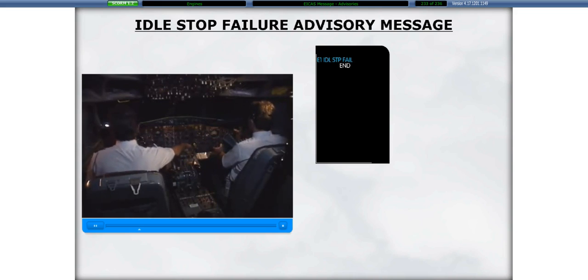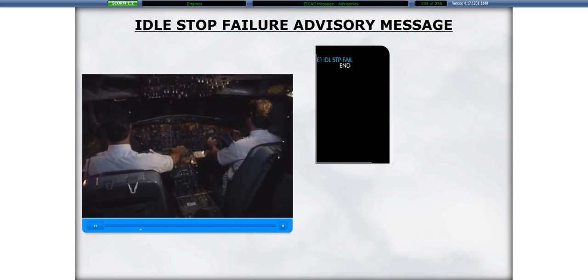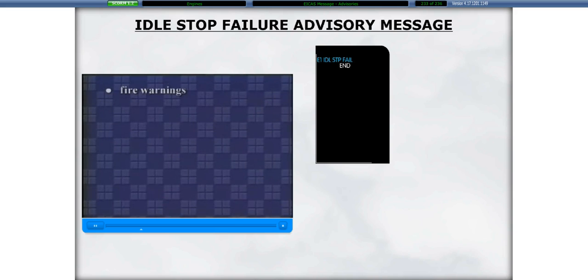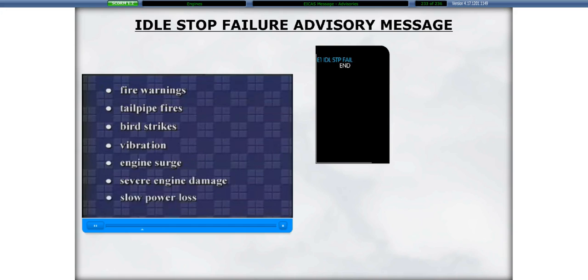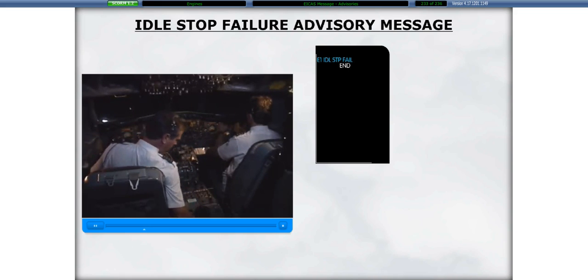But how? The objective of this video is to provide pilots with information to help them recognize and identify various engine malfunctions that have led to inappropriate crew responses and accidents in the past. These malfunctions include fire warnings, tailpipe fires, bird strikes, vibration, engine surge, severe engine damage, and slow power loss. In each case, the first priority is to employ the basic stick and rudder inputs necessary to maintain aerodynamic control of the aircraft. Remember, fly the airplane and then identify and respond to the engine malfunction when time permits.